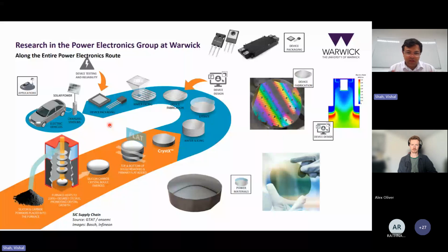So to quickly go through a fabrication line, for silicon carbide, the way that you make the wafers is different to silicon. In silicon, you'd have a vat of molten silicon, and you'd pull it from a crystal, and you could create a meters-long ball of silicon and chop that up. Silicon carbide, you have to start from a powder.